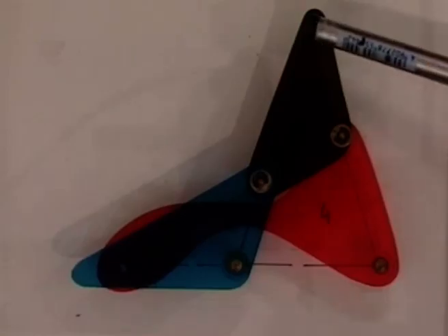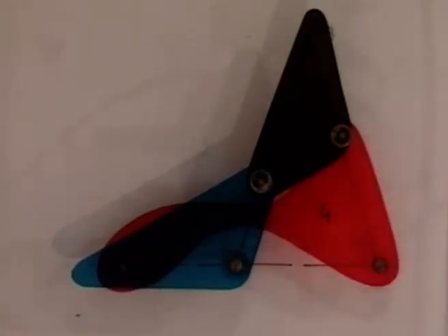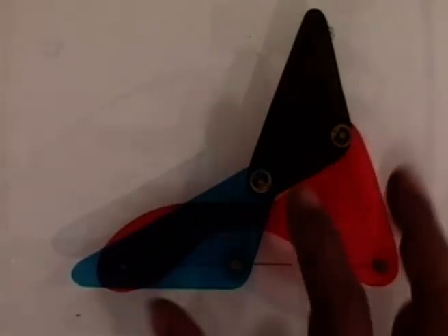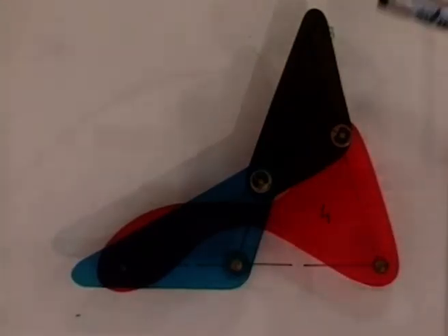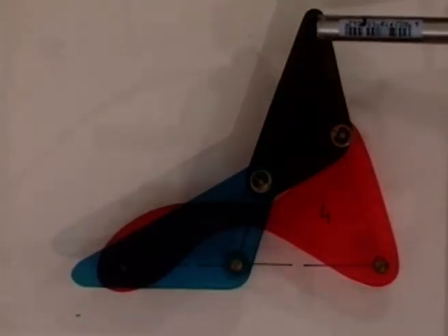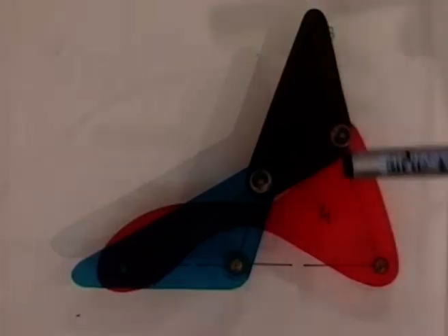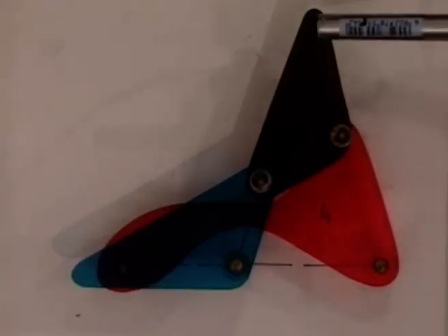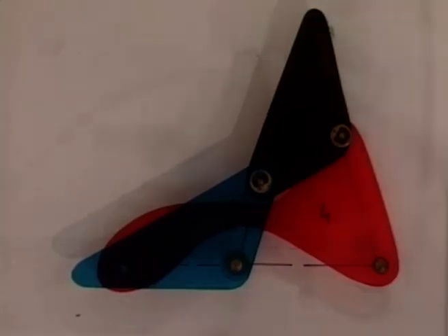So this is 1, 3 and this is 2, 4. Now, if we move this linkage around this configuration, because this point is P1, 3, that means link 3 is instantaneously rotating about this point, which does not move. This point has 0 velocity, as we will see when we move this linkage.